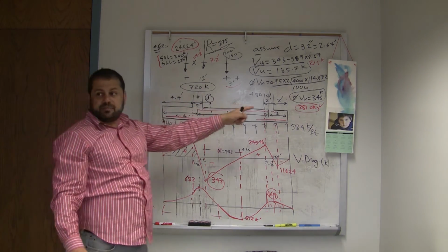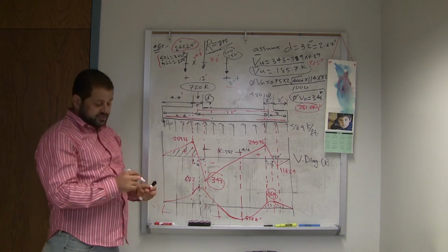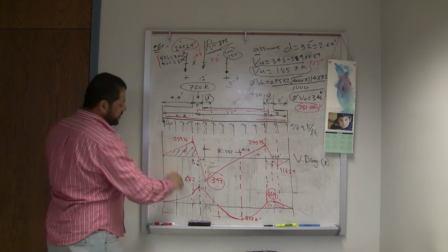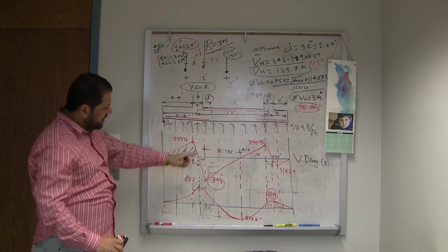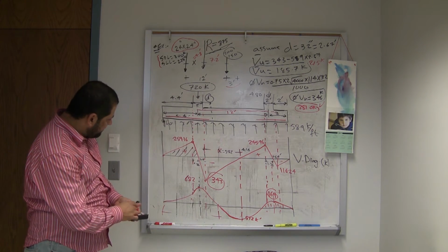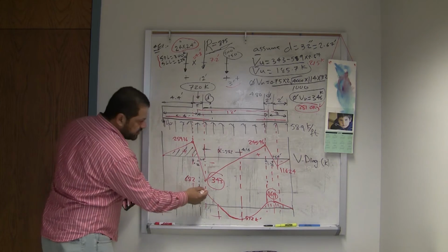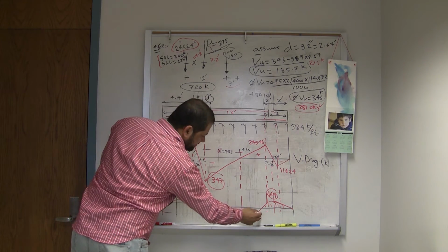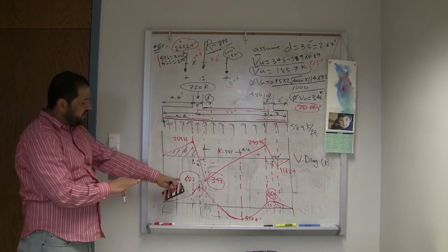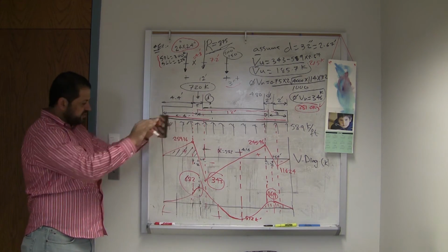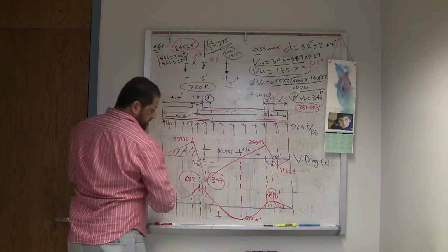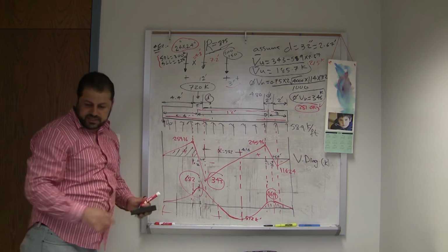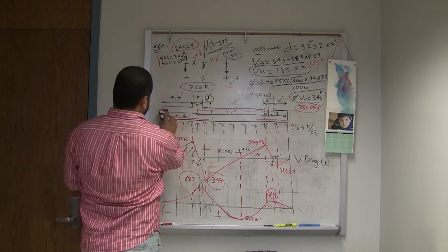After that, you need to check the punching. I will show you how you check the punching. Punching will usually be fine. Remember, the maximum moment we have is 682 here, negative, and 512 here. I'm going to show you one design, how we design for the 682, and it's for you to continue the rest. But let me also show you how you do the punching, and you can do it on your own.